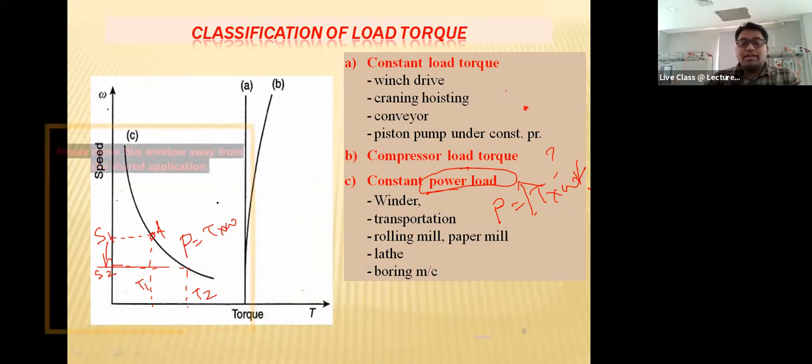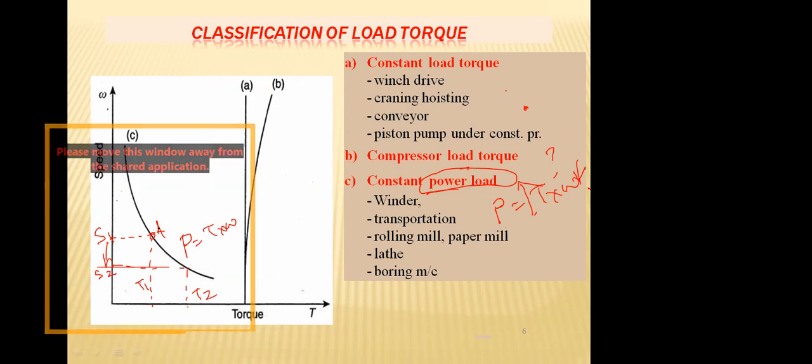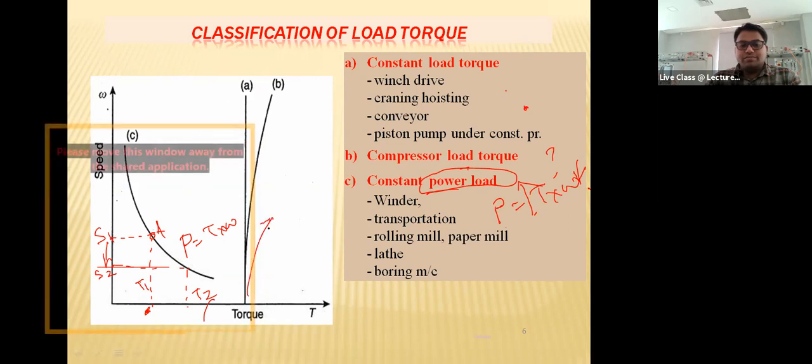As the cylinder becomes full of air, then the motor has to pump more and more energy to fill the little space that is left. Usually when a tank is empty, it is very easy to pump the air in, just like inflating a balloon, right? So the torque will be of nature B. The more it gets filled up, the more torque has to be applied.